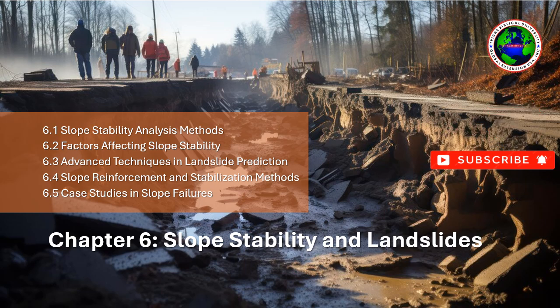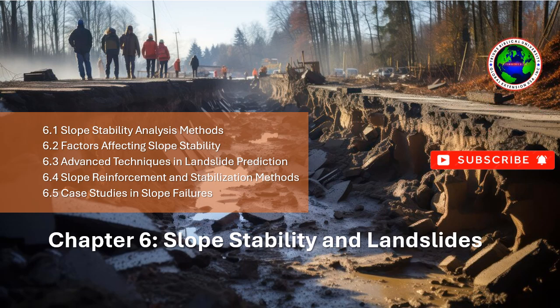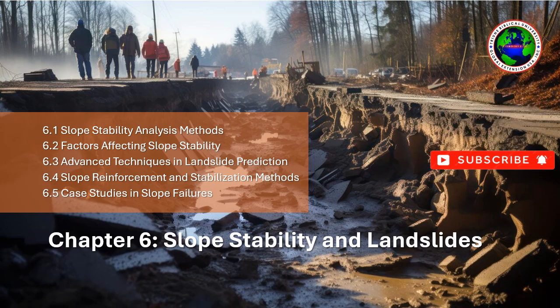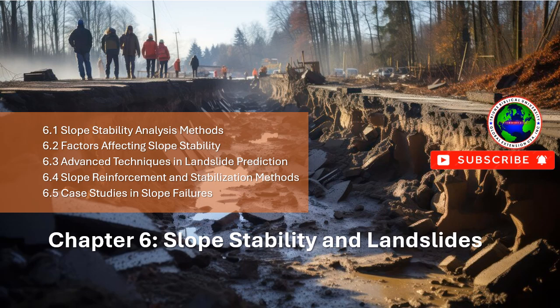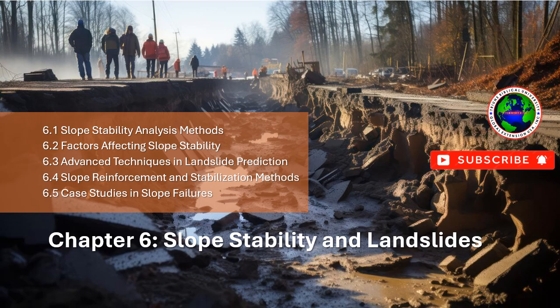Applications: used in combination with other stabilization methods to reduce the risk of water-induced landslides. Effective in areas with high rainfall or where surface water accumulation is a concern. Advantages: reduces water-related instability by preventing the buildup of excess pore pressure. Can be implemented alongside other stabilization techniques. Helps improve soil cohesion and minimize erosion.